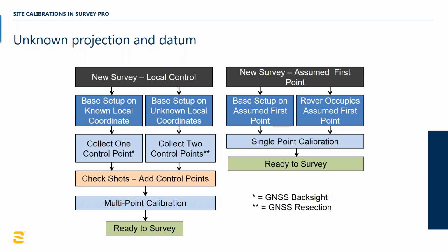Now, if you stored a stakeout point and then went and did anything that changed, whether that's added more calibration points and resolved the calibration, or it could be changed a rod height in the edit raw data and readjusted the survey. It could be a number of things that potentially change the current coordinate for a point you had previously staked out.